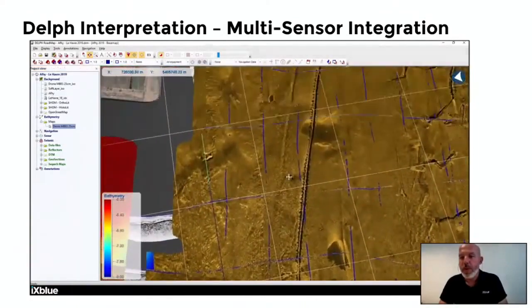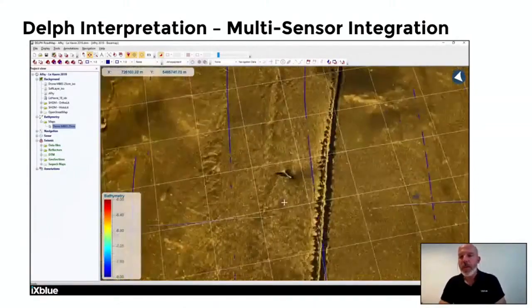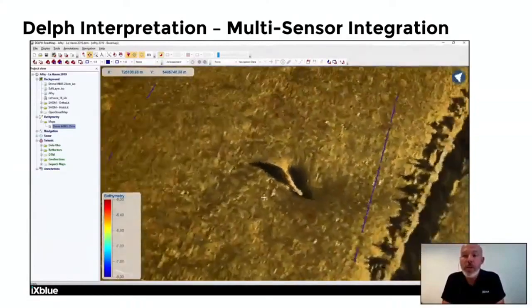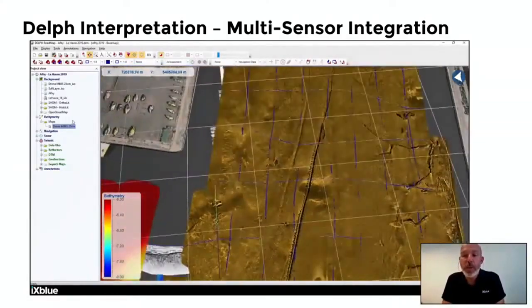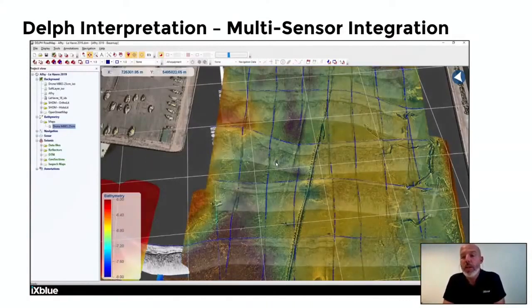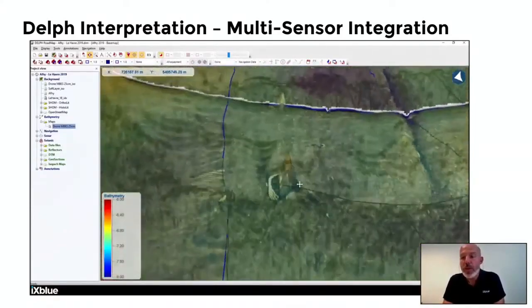Further on, now we are adding the side scan information. So we are overlaying the bathymetry with the side scan mosaics. And this is very helpful because we can already combine not only the high resolution aspect from the side scan, but also the relief from the bathymetry. So this is already a good QC about the target location, if the positioning was done right, and also helps revealing all the bumps and holes, the real topography of the seabed features we see in the side scan.